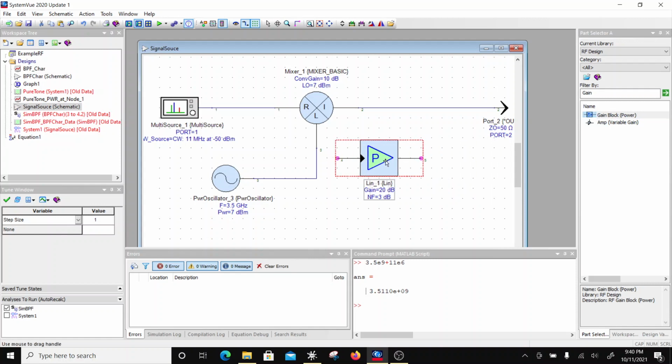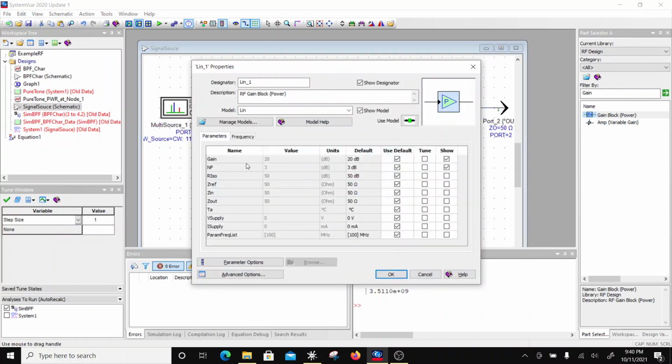Okay, so let's experiment with this. Okay, I haven't ever made a distinction. So I want a gain of 60, right? So if I put minus 30, is going to give me plus 30, right? Noise figure here is really bad. Let's say 7. Okay, and reverse isolation. So gain is 60. Then this reverse isolation for stability should be around. That's why we split it up.